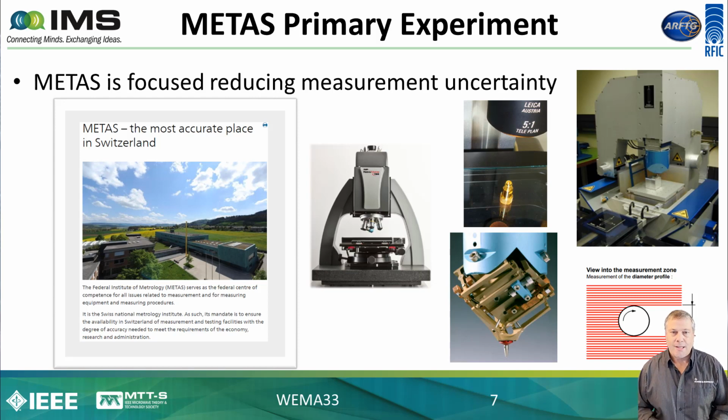I'm just showing some pictures in this slide, but they have all the equipment to do the physical measurements, such as, of course, measuring distance or diameter of a conductor, but also measuring surface roughness of a conductor, as well as measuring the coplanarity of, for instance, a waveguide flange or the connector that needs to mate, the male and female connector mating plane. And in addition, other things such as the concentricity of the center conductor and how round is something. So they have the tools, these National Metrology Institutes, they have the tools that are needed for this type of experiment, and they are in the best position.